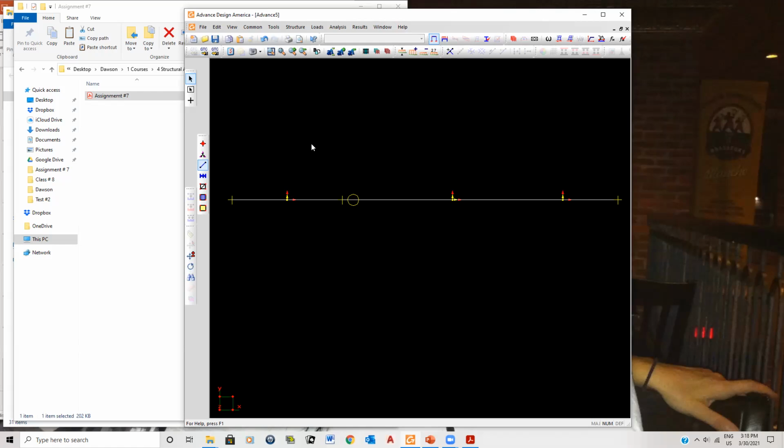Okay, but the thing is, I did try it out, changing 350 for another 350, and it didn't change any of the shear diagram, moment, or reaction. No, because the Young's modulus is the same for all the steels. You see what I'm saying? When it comes to structural steel, whether it's 350 or A992, the E is assumed to be the same value.